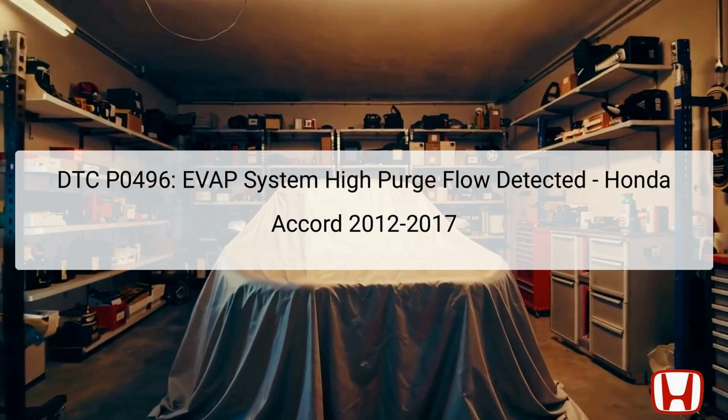The DTC P0496, which stands for Evaporative Emission Control System, EVAP, High Purge Flow Detected, indicates a problem with the vehicle's evaporative emission control system that is unable to manage the vapor coming from the fuel tank properly. This specific issue can lead to a higher volume of vapors being purged into the intake manifold than is normal.